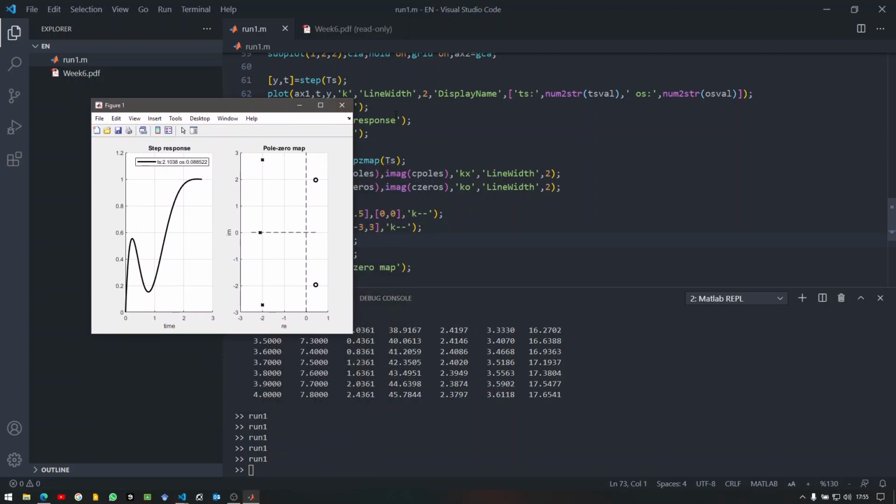Now, this is the tabulation method because it is fairly straightforward. You're defining your controller structure, you have the unit feedback structure, or it might also be not a unit feedback one, it could be any feedback structure. You're determining the closed loop transfer function in terms of the unknowns, and then you come up with a characteristic polynomial that is based on a second order polynomial and a residue polynomial that tries to equate the degrees of polynomials. And then we are looking at the coefficient equation problem. We're equating them and getting a result.